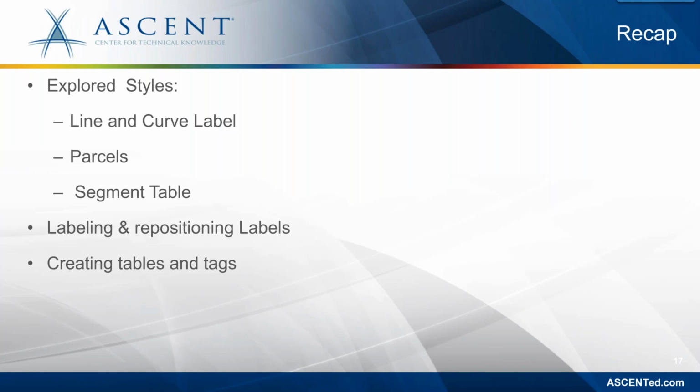We looked at editing these styles or creating a new style, in this case with the spline. We add an expression. And then we looked at labeling and repositioning these labels by moving them with the grips. And then we finally looked at creating tables and also creating tags for the different label styles.